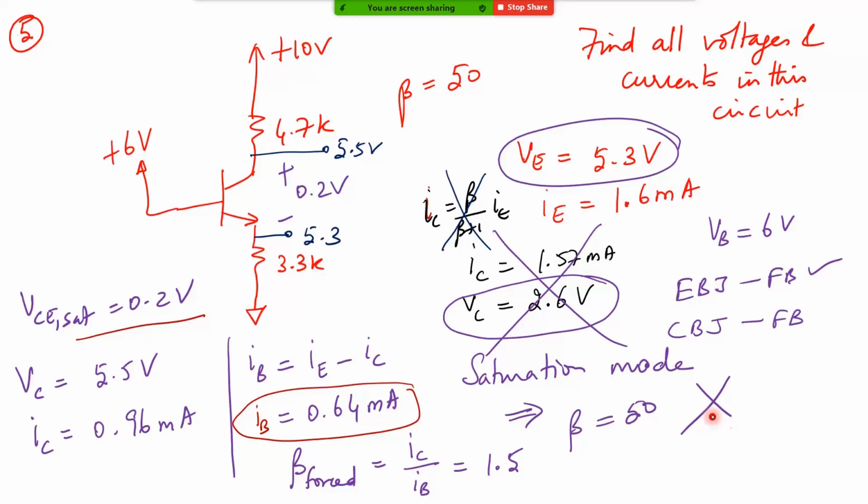So, always assuming that VBE is equal to 0.7 volt, is that correct? Always take boundary values. Sometimes you can say 0.6, sometimes 0.65, depending on what you are getting. If you saw in yesterday's class, I was showing you the data sheet. Let's say you are using the BC547. You will see that the voltage range in which the currents are happening is around 0.65 or something. So if you are using that transistor to design your circuit, you can just take 0.65 and design. Okay.